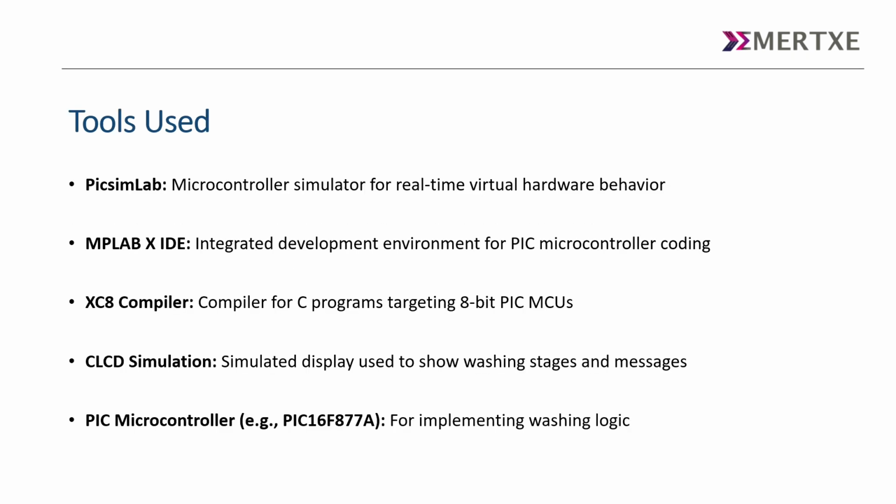Moving on, coming to the tools used here, one is PicsimLab. It is a microcontroller simulator for real-time virtual hardware behavior. It is a tool we need to install on our laptops to simulate the microcontroller in real time. The next tool is MPLAB IDE, an integrated development environment for PIC microcontroller coding. And the next thing is the XC8 Compiler, which compiles C programs targeting 8-bit PIC MCUs. The XC8 Compiler is used to compile the C programs that you write in your MPLAB IDE.